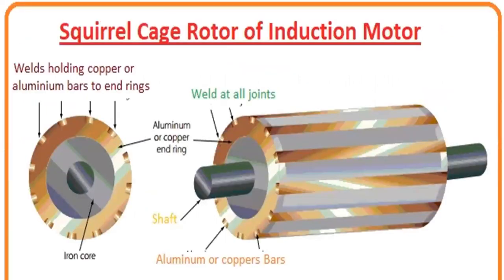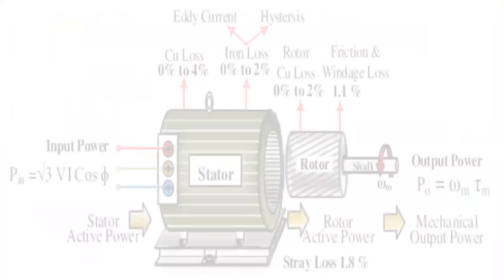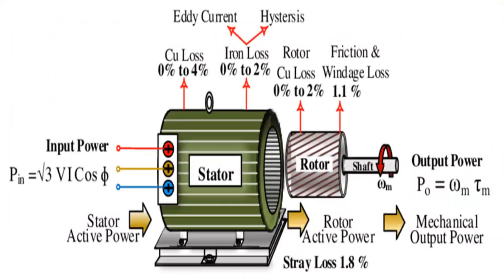In this motor, the stator is given a three-phase AC supply. The rotor is shorted inside through the copper rings at either end. When the stator is given a supply, it produces a rotating magnetic field which rotates at synchronous speed. The rotor then starts rotating, trying to achieve the synchronous speed, but it can never achieve it. The difference between actual speed and the synchronous speed is called slip. The slip, when represented as a percentage with respect to synchronous speed, is called percent slip.